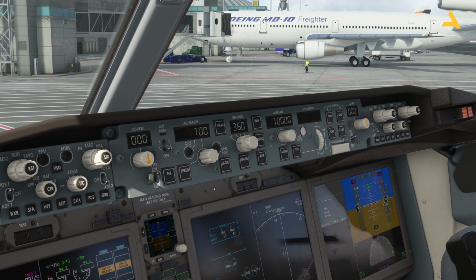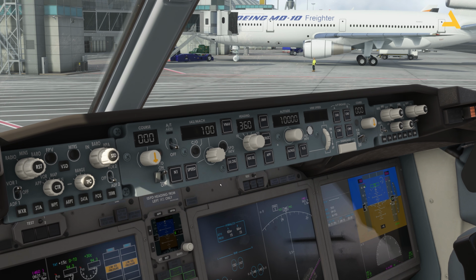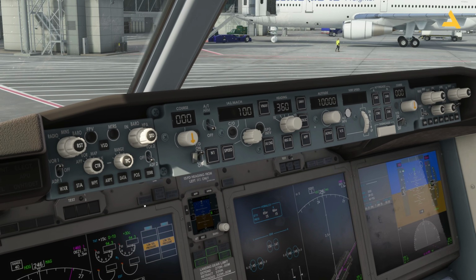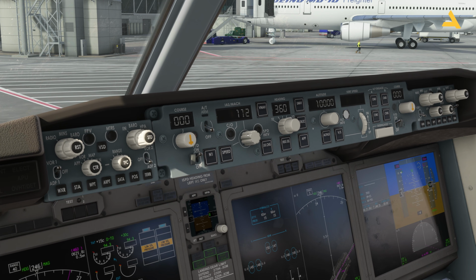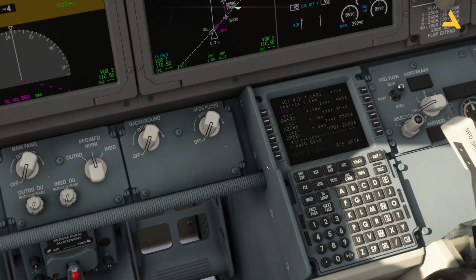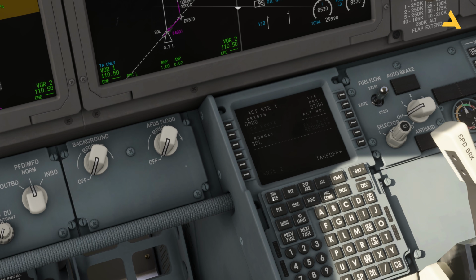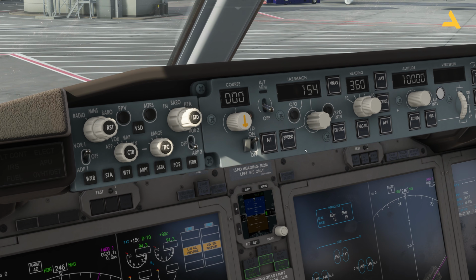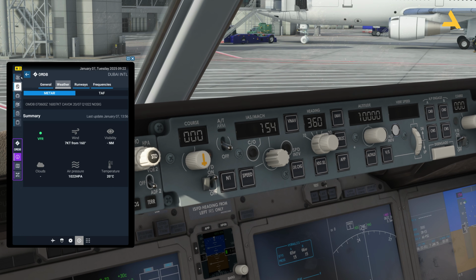Just turn it on, because if the flight director is on, then the plane will follow the flight plan, which is over here. Otherwise, it will not. Now, the speed, you will set it to 156 knots because this is the speed you want to achieve right after the takeoff. This is the V2 speed. Let me just check it again. 155. That's it.